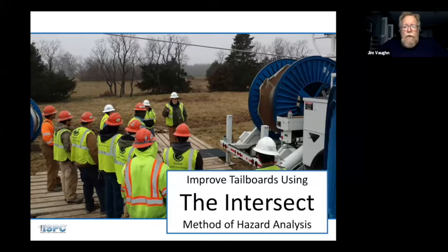The plant was shut down. The motor control center for the 4 kV gear was still energized on the bus, but they locked out and opened every one of the breakers. If you're not familiar with metal clads, the breakers slide out and give you access to the cable terminations on the inside. So everything was switched out. For 2 weeks, they had been working on replacing these things.